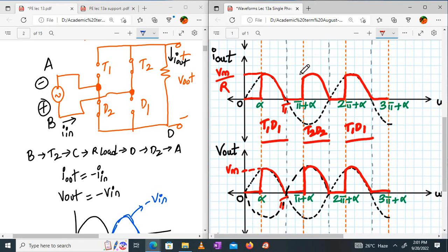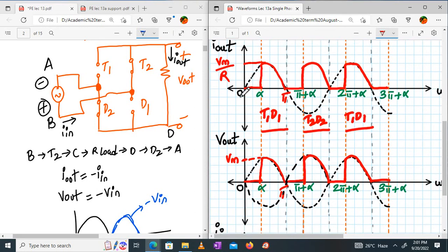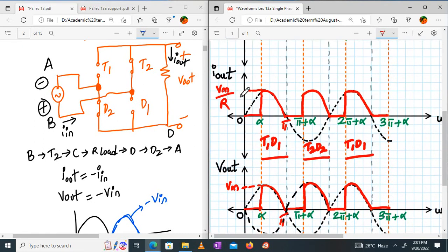Have you drawn it? And please, whenever you draw it one below the other, all the dotted lines should be visible to you only. It's just for reference. You don't draw dotted lines very dark, very light. That is just for reference, so that the actual waveform shape will be proper. Or else the positive half cycle will be very long and the negative half cycle will be very short. It should be equal. It's a periodic waveform. Any doubt in understanding? The single phase semi-converter with resistive load, very, very simple. No challenge at all. And from here on, your cycle will repeat itself.